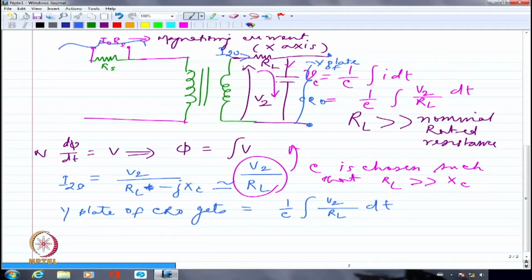That's the reason why, if I want the magnetizing current really in amperes, I have to divide it by RS. RS I have measured, so it's not a big deal. So I am rather getting IM multiplied by RS in volts. So ultimately I have to scale everything to get the hysteresis loss. So this is essentially the principle behind the BH loop. I hope you understand the principle behind the experiment.